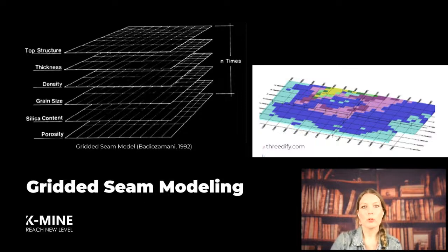Grid-based modeling approaches work by first calculating new interpolation points as a weighted average of the original geological data, and then forming grid spaces to define geological domains. These methods rely on a series of two-dimensional matrices where each grid represents either surfaces or specific values. The blocks of these grids remain consistent sizes in the x and y directions, often rectangular, but in the z direction there is just one block per bed with its height determined by the bed thickness.